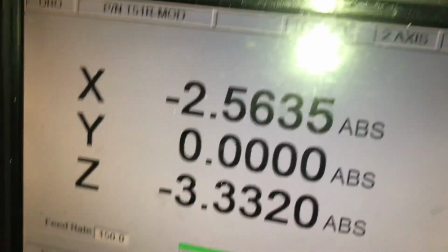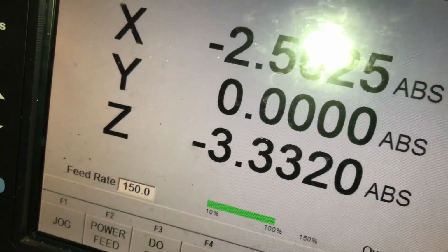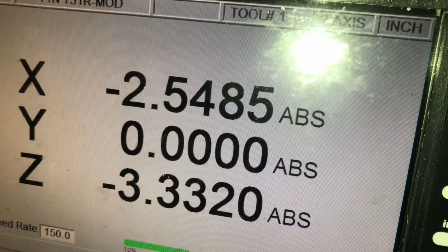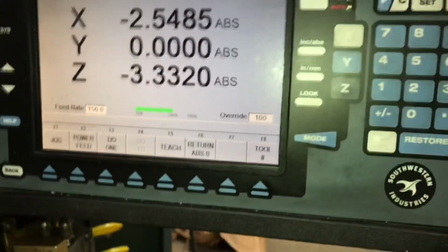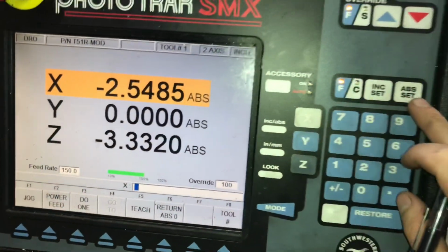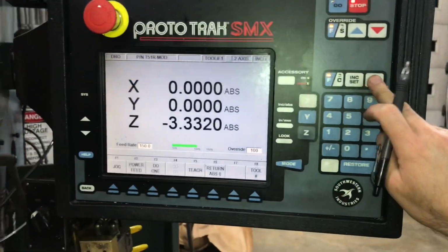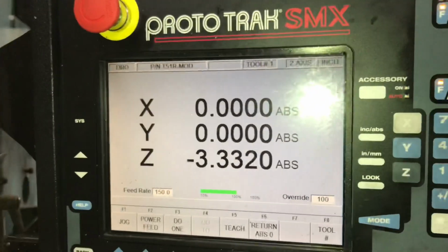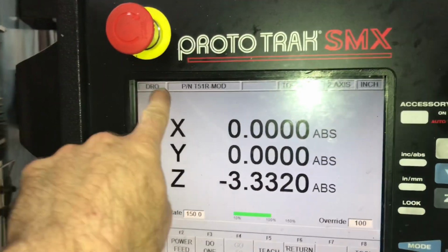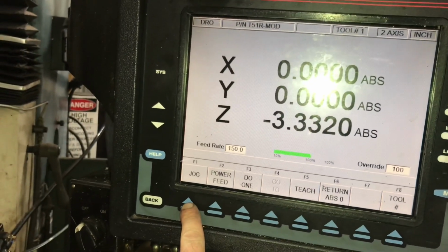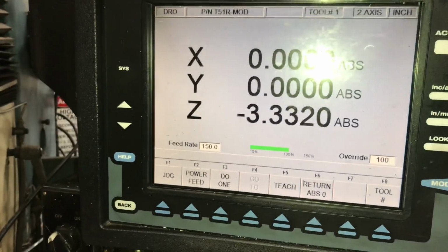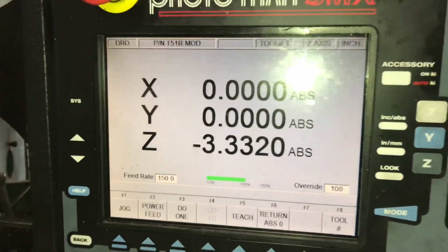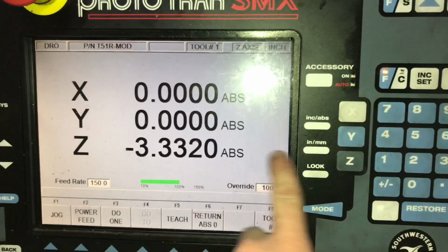So we're going to go to negative 2.54, you go to 85, or you can go to 90. So we'll do 85. And just zero that out. Also keep in mind, you can only zero these out in the digital readout mode and not in the jog mode. If you press these buttons when it's in jog mode, it moves the tool table. And it would move the Z-axis if my 3-axis part was working, but it doesn't.